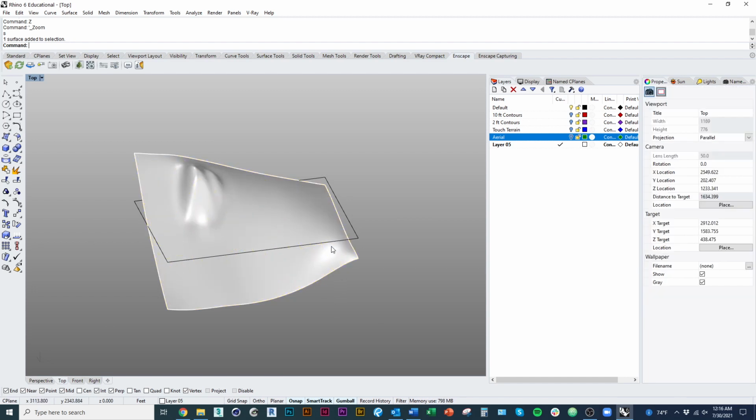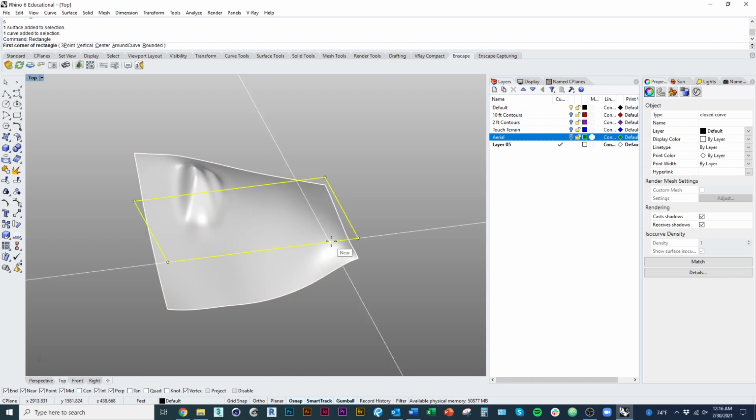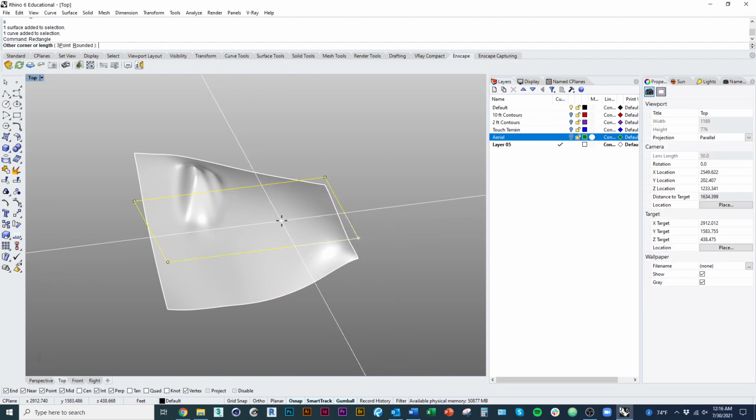Now this surface is literally 1/4 of an inch, so it should be the exact dimensions we want our model to be. Now I could make another outline, and this time I can enter how large I want my model to be in inches. Because my file is in feet, which you can see down at the bottom, I have to write the quotes symbol.